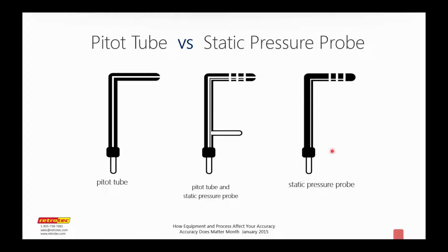Right, and thank you, Joe. Also, Joe, I just wanted to mention that we also need to make sure that this one is actually taped in there. Oftentimes, it's a really good idea to make sure that this piece right here is securely placed or taped in, so that vibrations along that tubing don't cause bad or inaccurate readings.